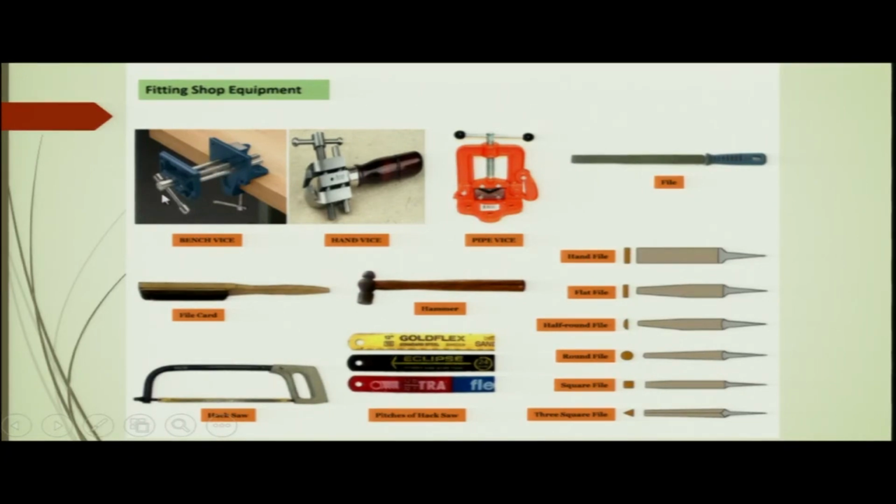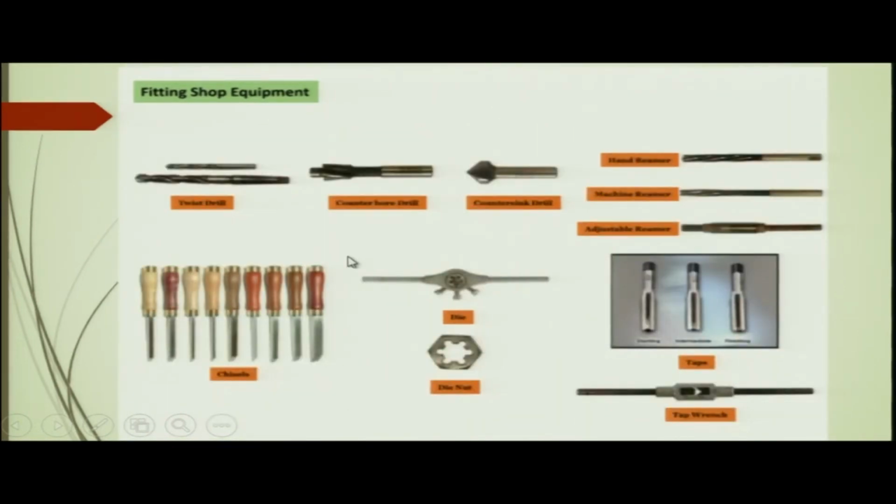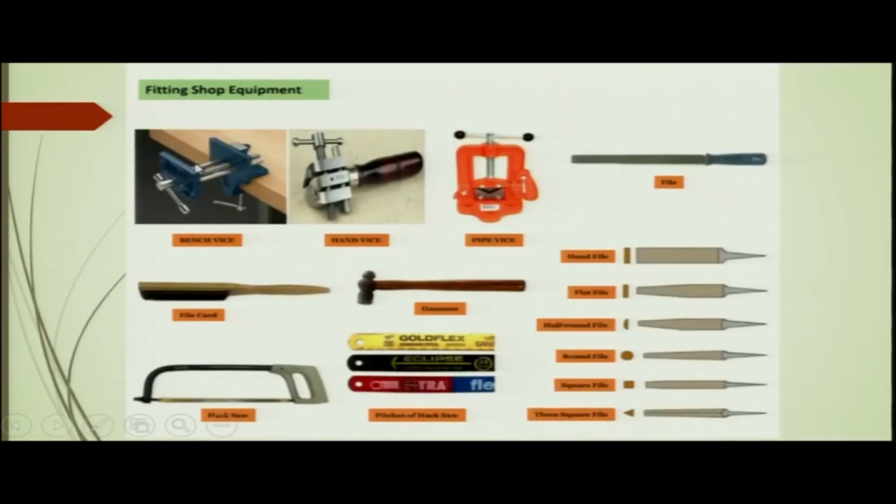Okay. If you rotate the handle here, by rotating this handle you are rotating the lead screw, and this will be working as a screw and a nut, and this nut, which is the jaw, will move closer to the other jaw, and in between you can actually fix a part. Let us say this is a workpiece, square workpiece, round shape workpiece, whichever workpiece you need to file for example, or drill a hole, okay, and so on, or cut.